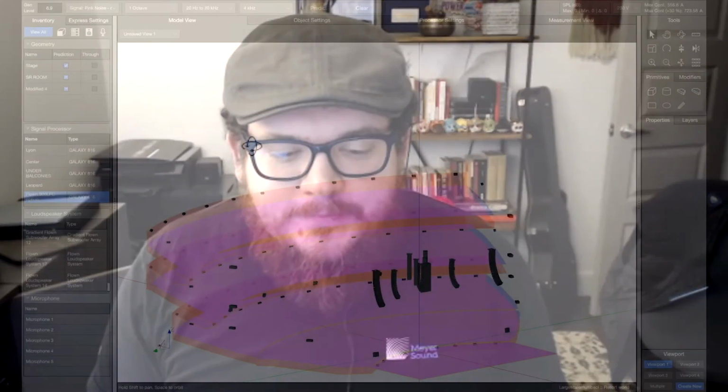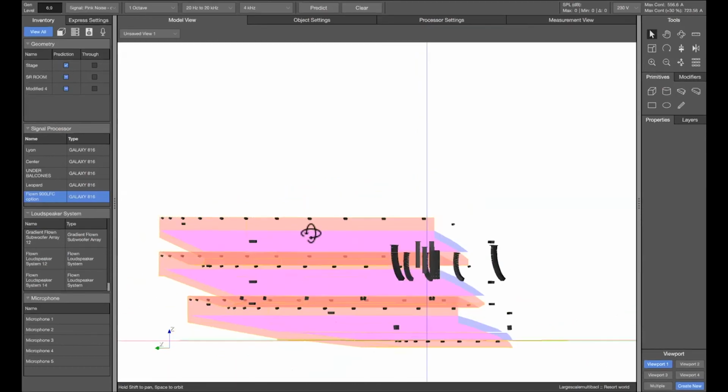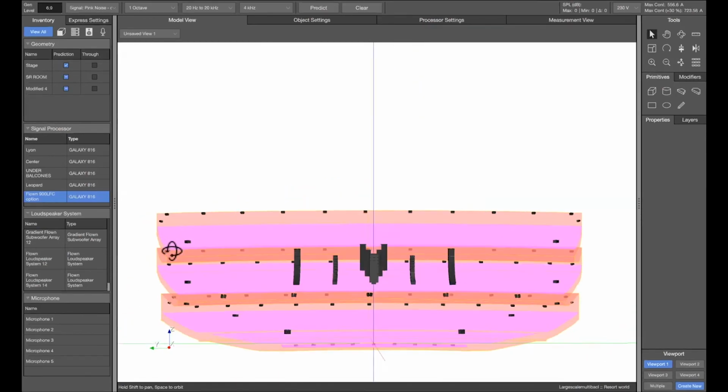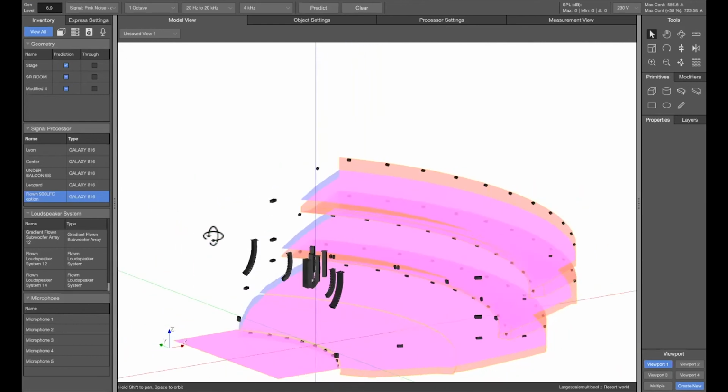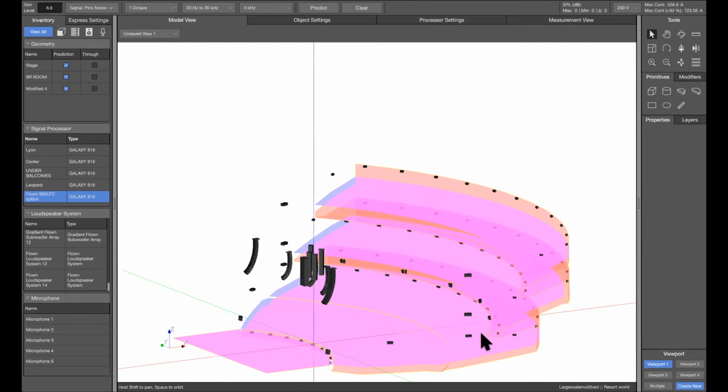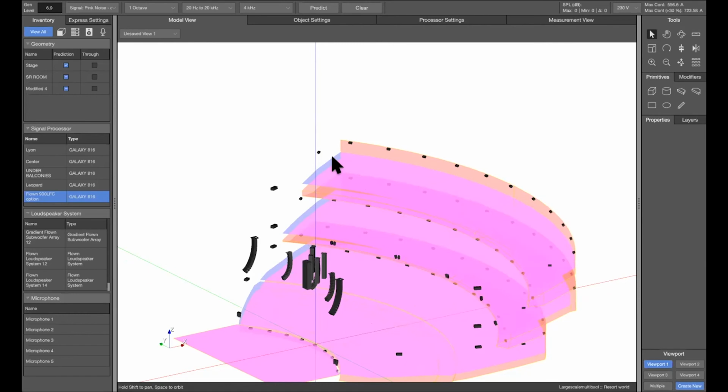I want to hit home these fundamentals. We've been doing a couple of big, large-scale systems for these giant multi-balcony speaker systems. This is an 8,000-seat auditorium, or over 8,000 seats, I believe. This is one of those very large-scale, wide fan-shaped rooms. And for side surrounds in a room this size, it's very difficult to get that throw from here to this speaker. So what we ended up doing for this design is actually using a Leo for a side hang.